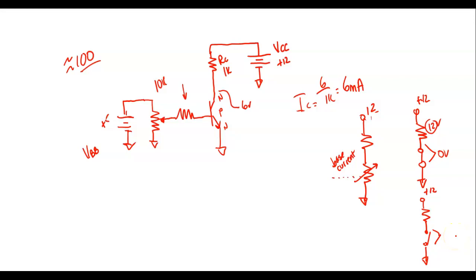So how much resistance does an open switch have? Infinite. How much current flow is there in the circuit? None. So if V is equal to I times R, then V is equal to 1K times 0. So how much voltage would that resistor right there drop? 0. If it drops 0 volts, that means 12 volts is sitting right there across the open switch.